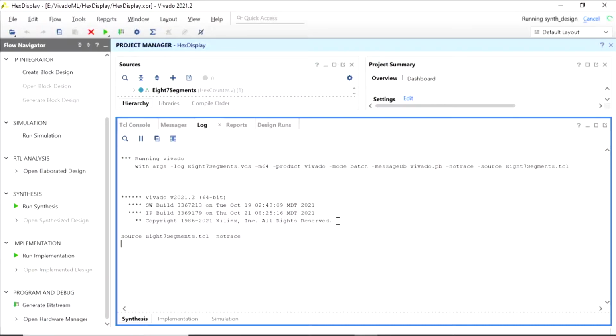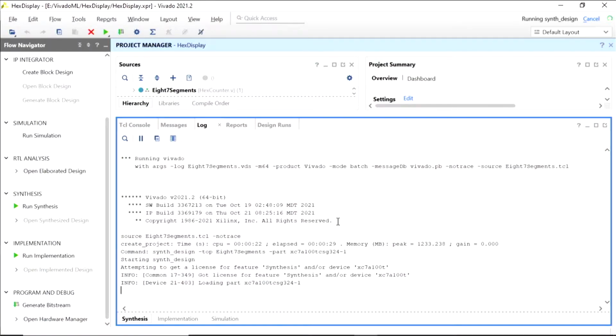But, you know, it's nice to see something, but it's not always an indication that everything's working fine. And if you end up in that situation where you're stuck on synthesis, one method is exit Vivado, delete everything but your source code and the project file, the main document for the process, and then start fresh.